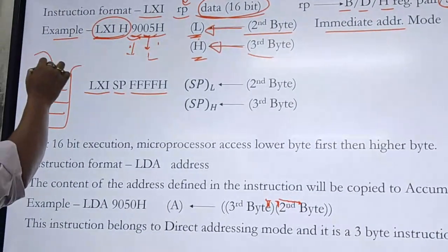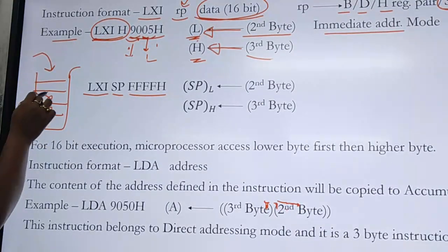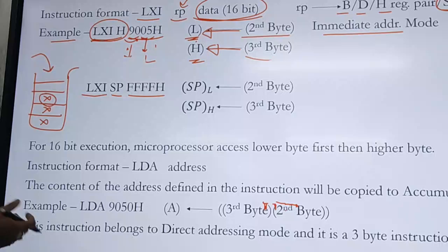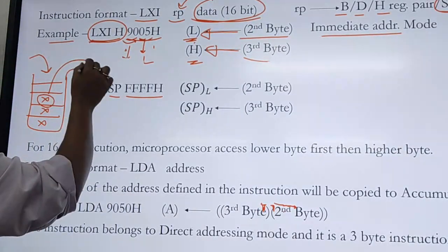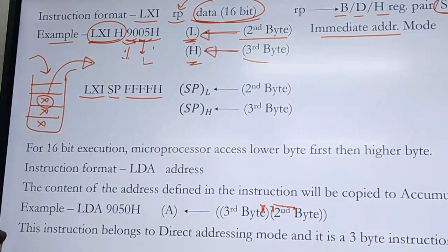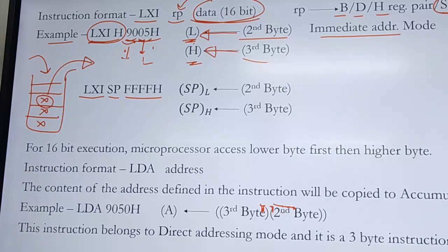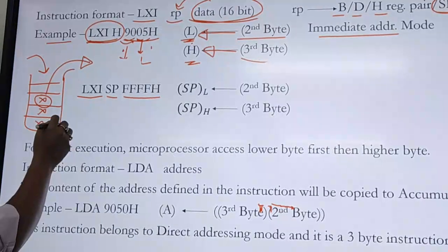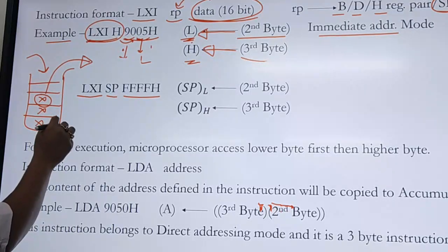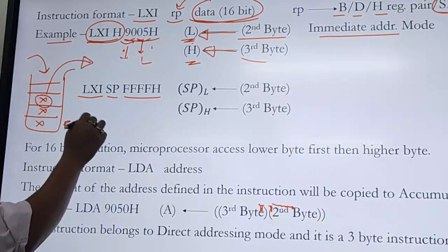Here all the data will be entered in one direction and stored one by one on top of the stack. Whenever we retrieve data, meaning pop the data from the stack, the top-most data will be retrieved first. So this is called the last in first out algorithm. How do we define the stack in the microprocessor system? The first memory location should be defined as a maximum value like FFFF.